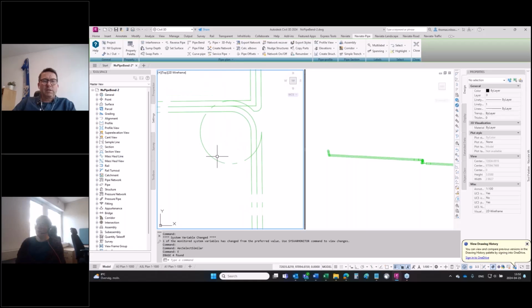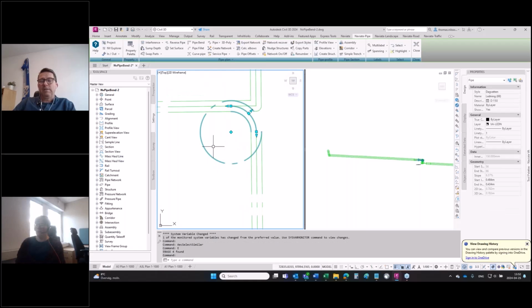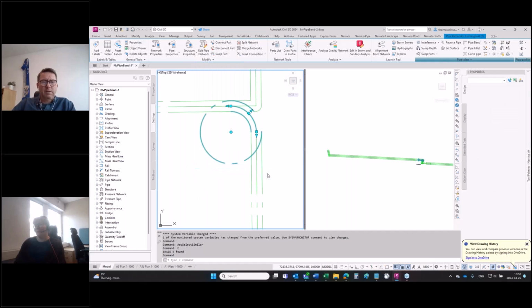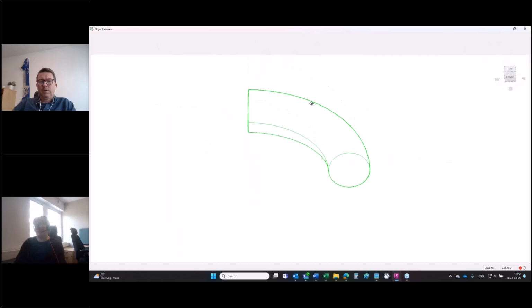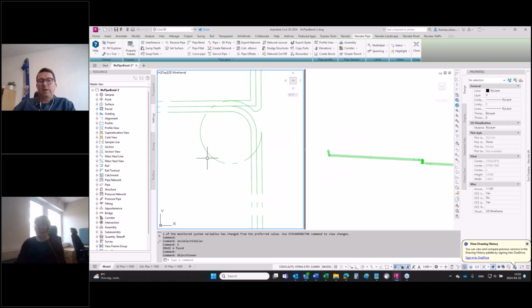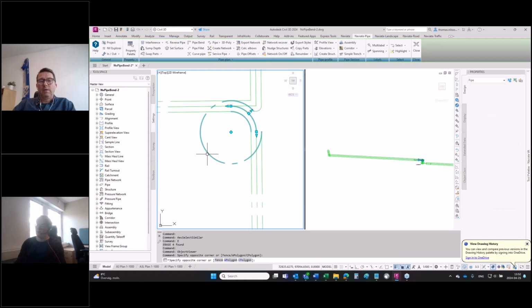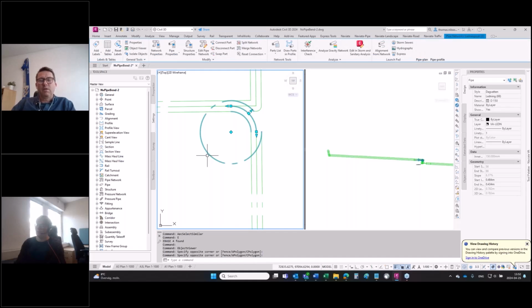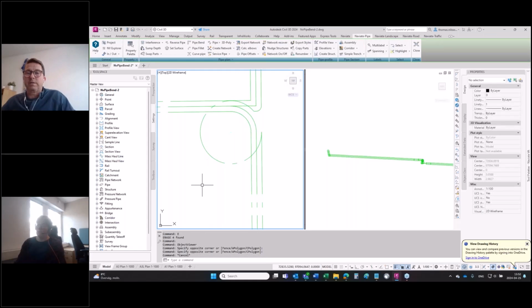And I think that I now actually ran into one of the strange things that Civil has. So this is not an error. I think you would consider it being an error from us, but I think that this is actually an error in Civil. Yeah, because it is correct, but sometimes Civil displays a curved pipe with the wrong direction of the arc. Not much we can do about that one, I'm afraid, unless we do solids. It's going to work.